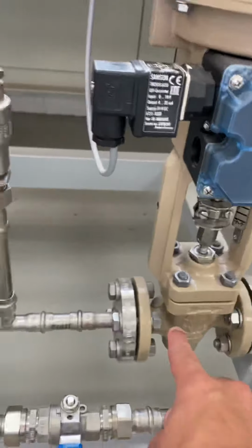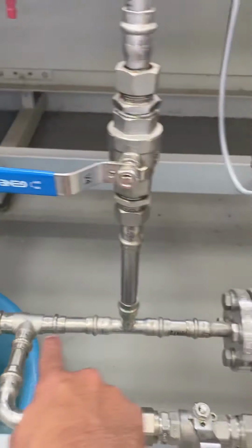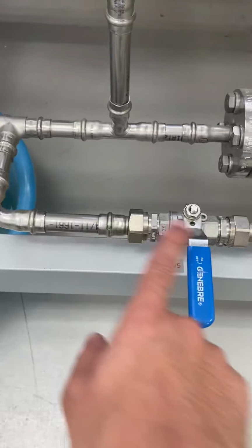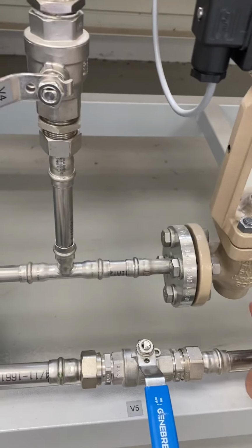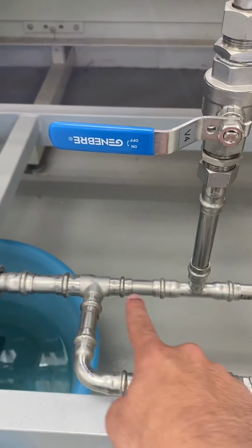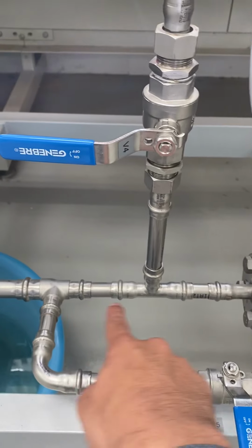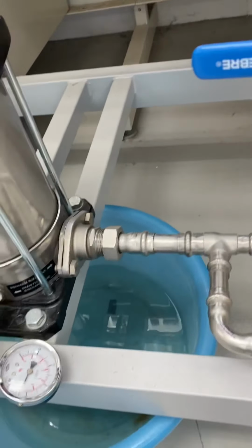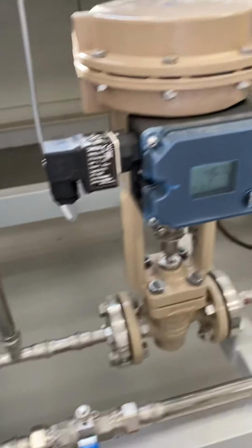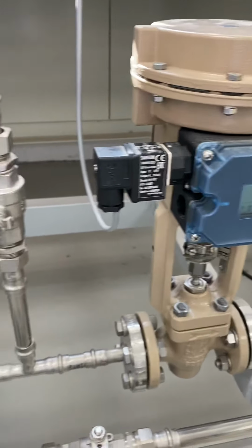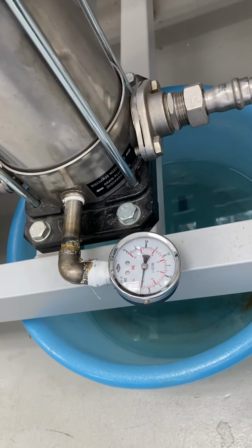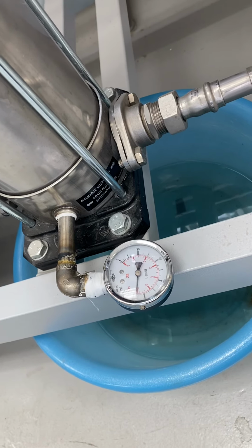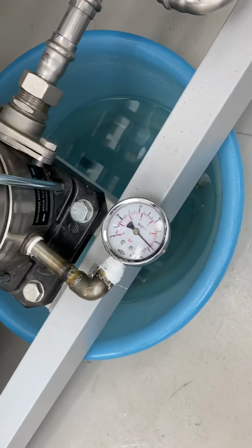Nice. That's why at this portion of the pipeline, and this pipeline is closed, this bypass valve is closed. Now the more you close the valve, the more discharge pressure of the pump we will see. But the more we open the valve, the more water flows through the discharge, and that causes the discharge pressure to decrease. The discharge pressure starts to go down. But now at 10% it reads around 6 bars, and alhamdulillah.